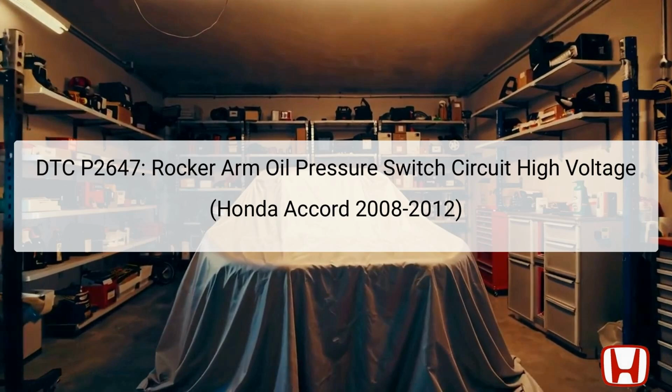The DTC P2647 indicates a high voltage condition in the rocker arm oil pressure switch circuit for all Honda Accord models from 2008 to 2012, except those designated as partial zero-emission vehicles, PZEV. This diagnostic trouble code, DTC, typically relates to issues concerning the VTEC system, specifically involving the oil pressure switch responsible for regulating oil flow to the VTEC rocker arm actuators.